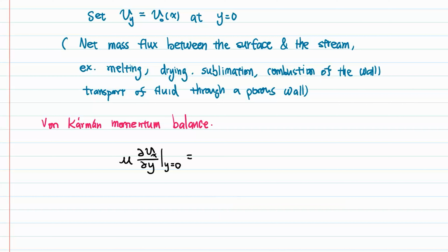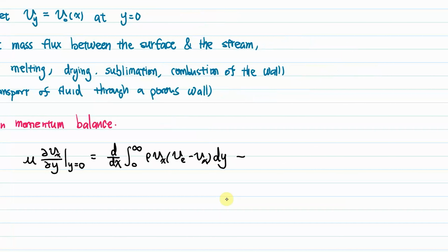Or let's say the force applied from the solid surface to the fluid equals to, the first two terms would remain the same, so d dx, integration from 0 to infinite, we have rho vx times v sub e minus vx dy. And we also have the same term d v sub e dx times the integration from 0 to infinite, rho v sub e minus v sub x dy.